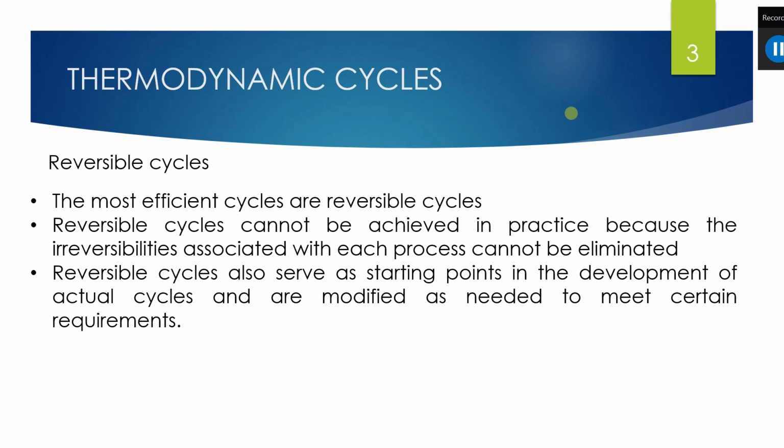So why are we interested in reversible cycles? Because reversible cycles are the more efficient cycles. Also, reversible cycles cannot be achieved in practice because of the irreversibility associated with each process. When a process is happening, there are many irreversibilities due to heat transfer, work transfer, etc., and those cannot be eliminated completely. Because of that, reversible cycles are ideal cycles and cannot be achieved in nature.